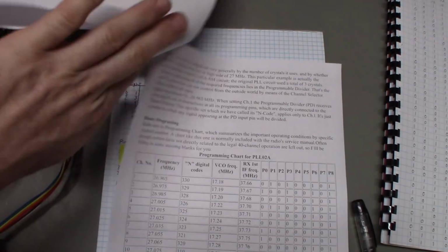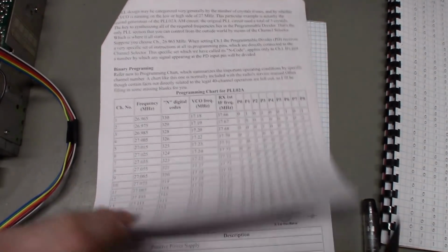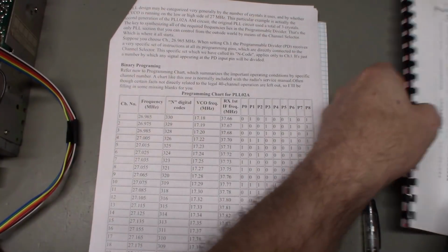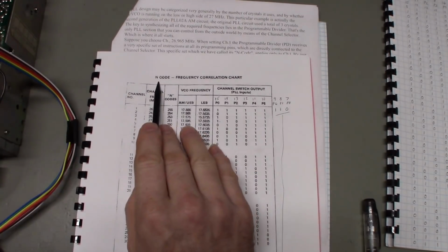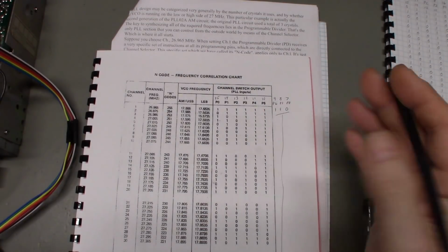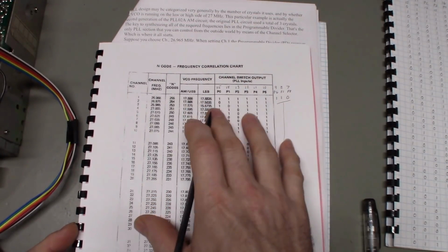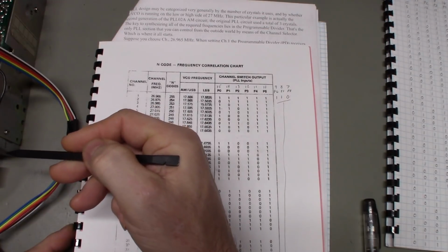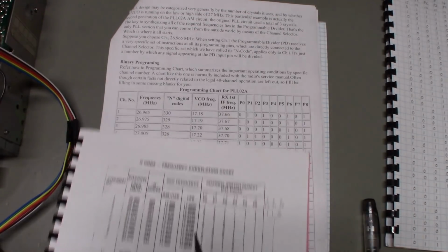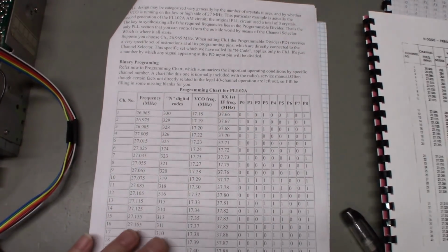The other thing, if you're working on a radio, so here's a chart. This is all off the same website, but this is normally known as a programming chart, or like a service manual for this radio over here, an encode frequency correlation chart, or if you're using a SAMS manual, and a lot of other manuals, they're known as truth tables. What these do is actually tell you, when you put the channel selector on the radio on a channel, what the programming is going to every one of those programmable pins on the IC. That's all this is.